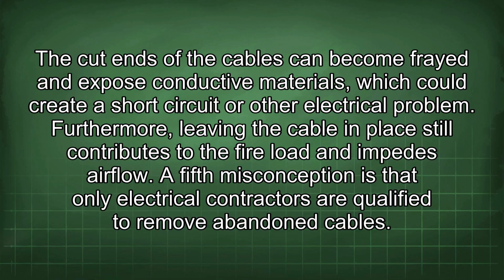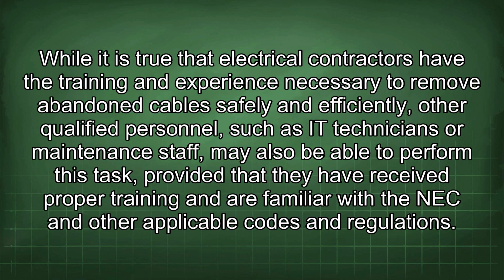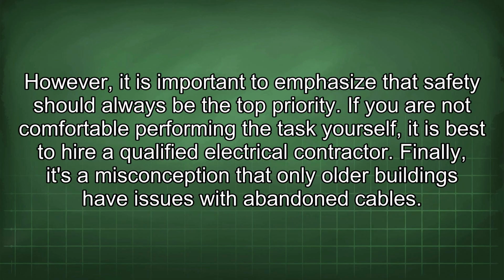A fifth misconception is that only electrical contractors are qualified to remove abandoned cables. While it is true that electrical contractors have the training and experience necessary to remove abandoned cables safely and efficiently, other qualified personnel, such as IT technicians or maintenance staff, may also be able to perform this task, provided that they have received proper training and are familiar with the NEC and other applicable codes and regulations. However, it is important to emphasize that safety should always be the top priority. If you are not comfortable performing the task yourself, it is best to hire a qualified electrical contractor.